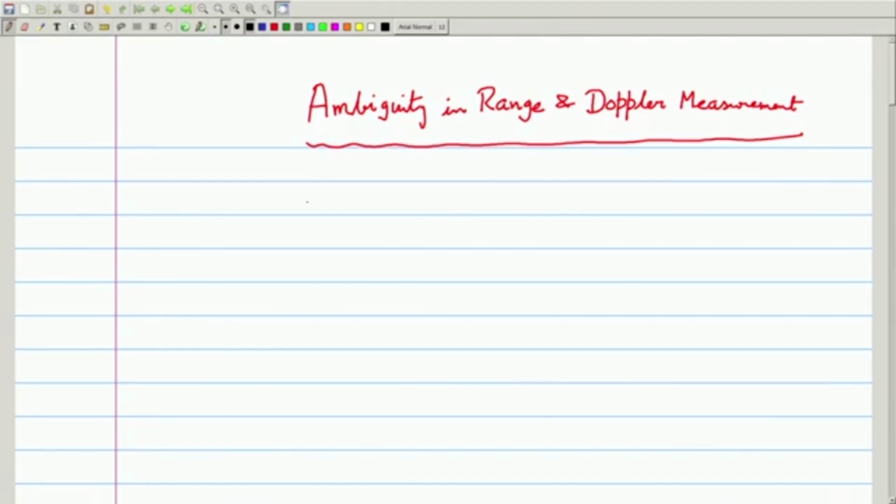If you look back again, that told us that the SNR of the matched filter at time t equal to T0, for zero mean Gaussian white noise, was given by 2Ex divided by the double sided power spectral density of noise.